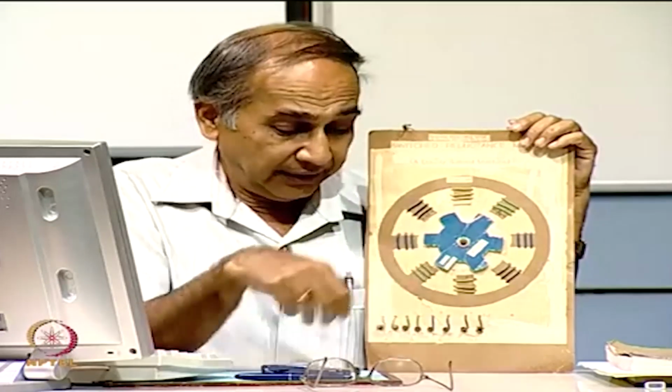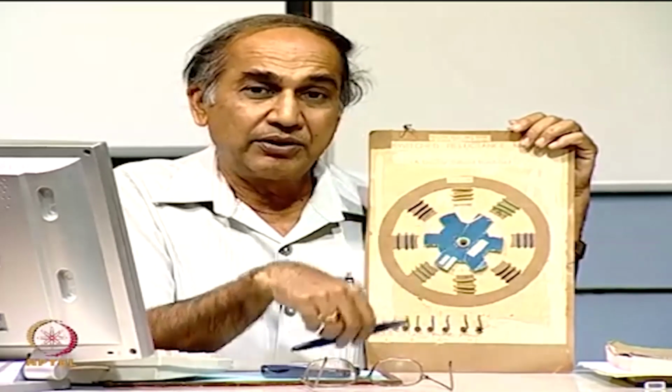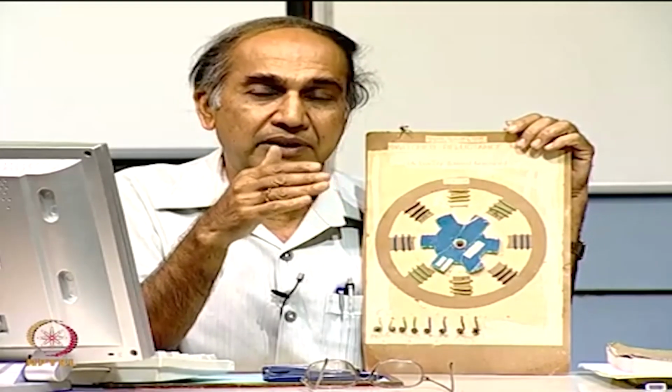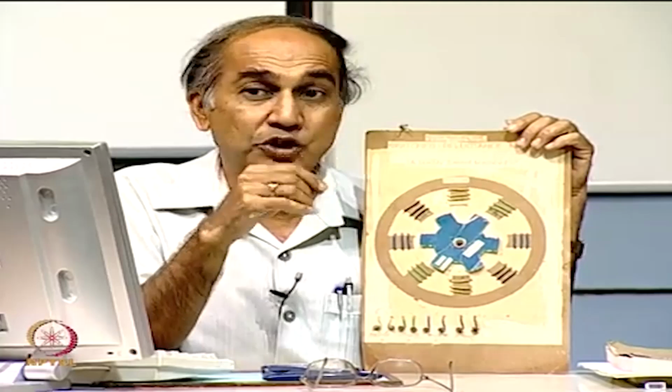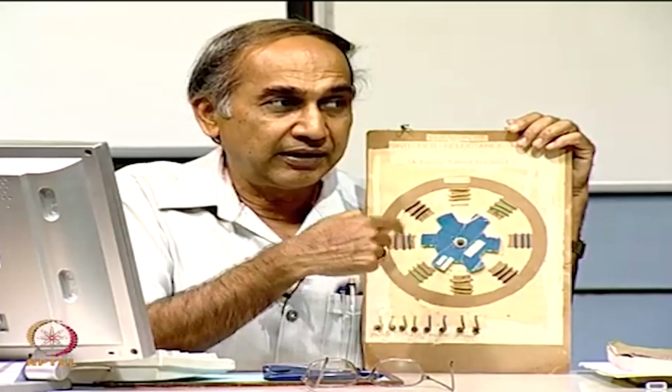So the principle of energy conversion or torque production requires you to know the inductances and their variation with theta and with I. Then you find that torque depends on the differential of inductance with reference to rotor position. If dL by d theta is 0, there is no torque.